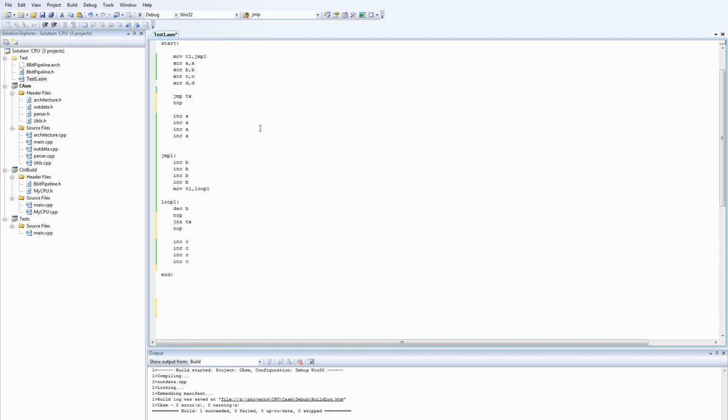Now, in a modern processor, what you have is hardware in the fetch unit, which is spotting the dependencies between instructions and doing one of 2 things. It's either delaying the execution of the dependent instruction, or in a higher end processor like a modern x86 processor, it's looking for alternate instructions that it can insert into that gap.